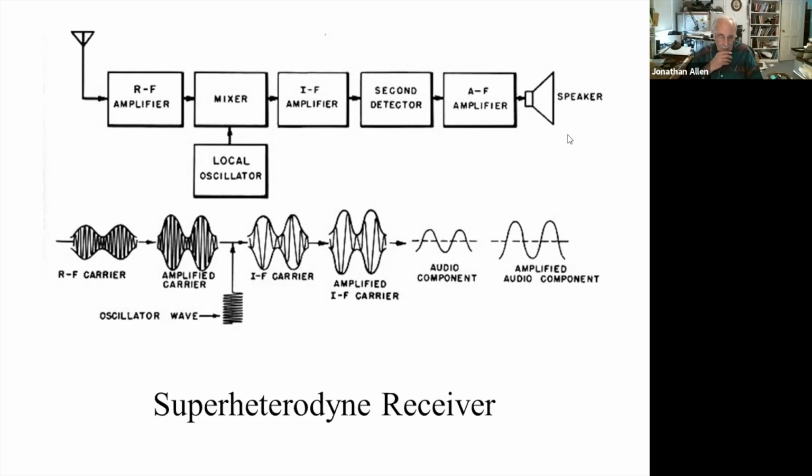Initially, the superhet was to overcome the poor high-frequency performance of contemporary tubes, whose gain fell off markedly at frequencies above 500 kilohertz, the bottom of the broadcast band. But the superhet yielded such superior performance that even after high-frequency tubes and transistors became available, it still, to this day, dominates virtually all receivers. And incidentally, this is the same Armstrong who is also known for electronic broadband FM radio. Guy was quite a hero.